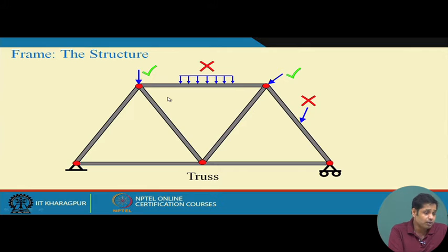Another important part is that in a truss we cannot have a force on the member. The force always has to be on the joints. And of course we have supports. Now consider a system, again a collection of these skeletal members, where the conditions that we had for trusses are released.